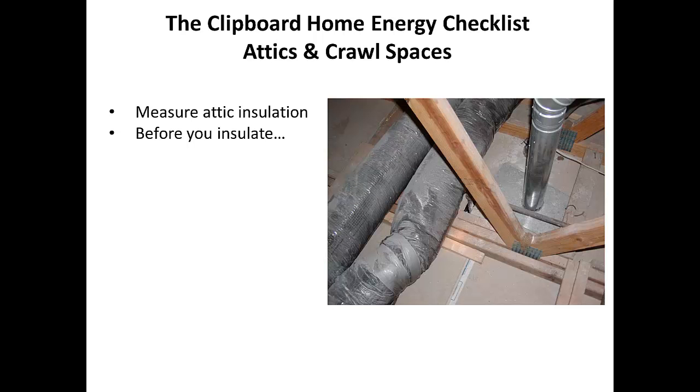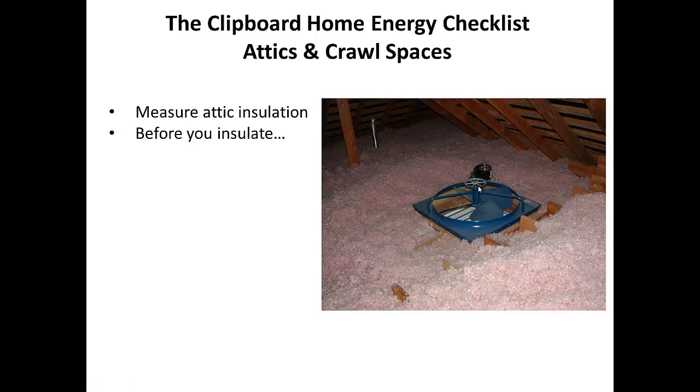Before you insulate, the professionals sometimes, in older homes, take out all of the insulation because, and I want you to watch where my mouse is going here, you see this little area here? This is in an attic with no insulation. And see this area right here? That's a hole that goes down into the conditioned area where it's trying to be cooled or heated in the summer and winter time. This is one of those culprits that you want to look for in the attic space.